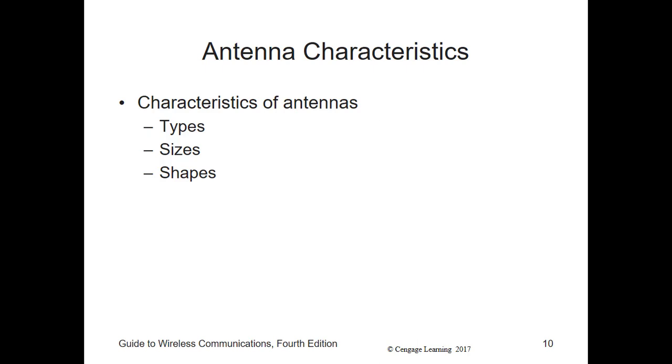Passive antennas are the most common type, and they're constructed of a piece of metal, wire, or similar conductive material. A passive antenna does not amplify the signal in any way. It can only radiate a signal with the same amount of energy that appears at the antenna connector, minus any losses introduced by the antenna cable and connector. However, as you've learned, certain shapes of passive antennas radiate the RF energy supplied by the transmitter in one direction, and consequently exhibit an effective gain that's similar to the amplification of the signal, called a directional gain.